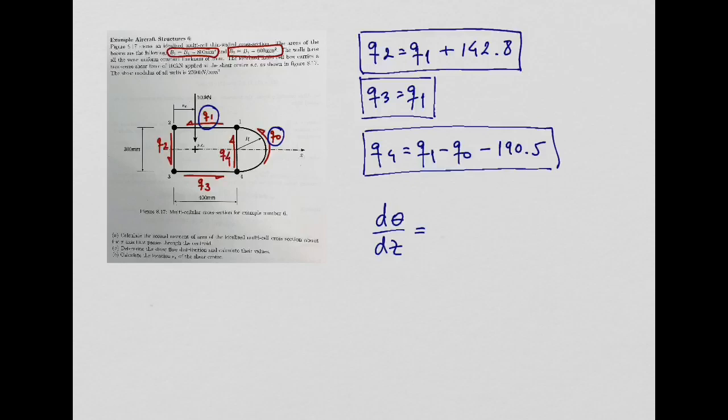All right. So, this gradient of twist, we derived this when we discussed the torsion, remember? And I told you the equation is 1 over 2 times the area of the cell times the modulus of rigidity, and then we need to do this contour integral, I'm quite sure you remember this, of q, the shear flow, over the thickness, integrated along the walls or the contour, right?